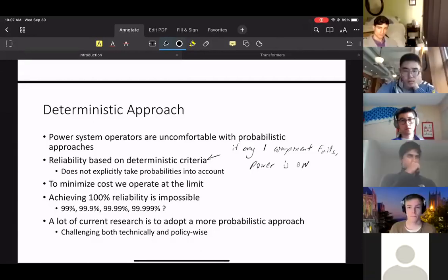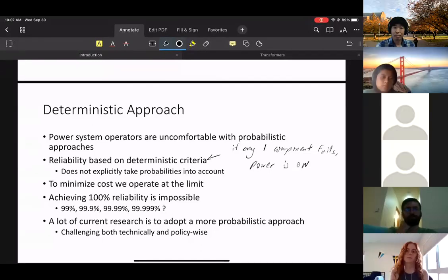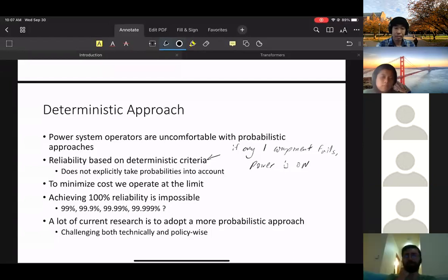Any challenges with this? In your mind, is that how failures happen in power systems? Do we have one-line failures? Failures are correlated with each other. You may have a common cause that causes multiple things to fail. Right, exactly, so failures are not independent. If I have a windstorm and my line fails, the next line to me will also likely fail. This kind of N-1 deterministic interpretation misses a lot of failures that happen in practice. If a fire comes along and I have 2 transmission lines going fairly close to each other, both are gone. So the failures are no longer independent, and the failure mode is actually quite complicated. Just ignoring them doesn't work anymore, and we see this in practice.